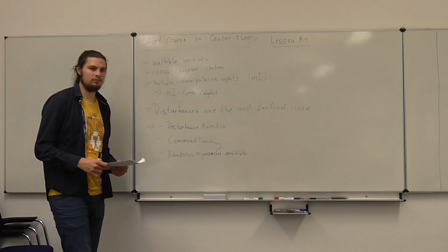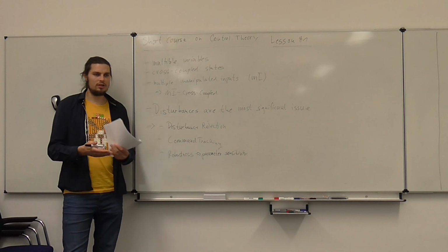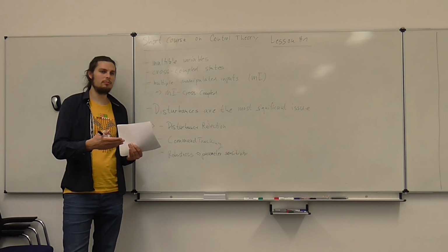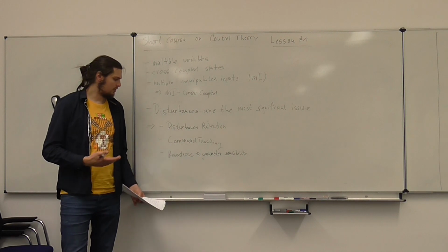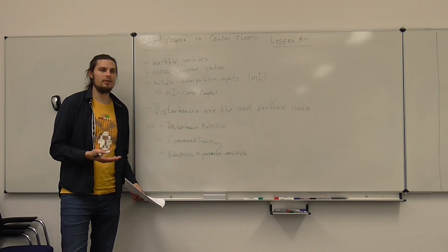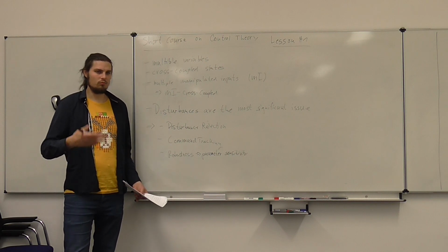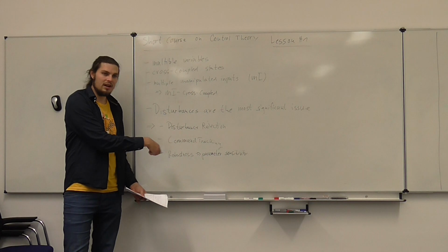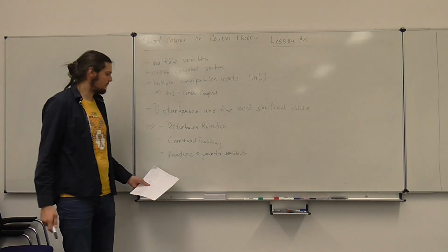This applies to every parameter of your system, for instance, for your current control, your Rs, your Ls. How well do you need to know them in order for your system to work? If you know that your system still behaves very well with even 30% parameter estimation error, then you can tell that's robust enough for the application. That's what you need to find out.